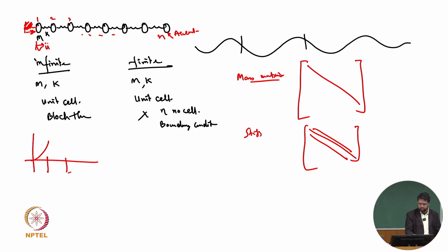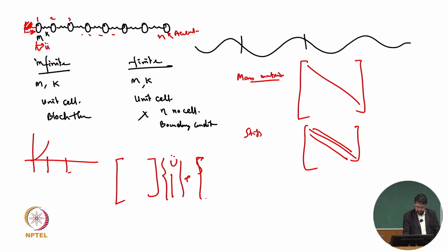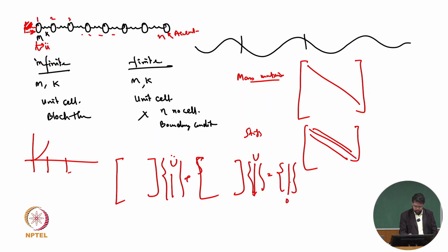Okay, so if that is our objective, then what do we have to do? We have to apply the force at the first node. We can write the mass matrix into u double dot, that full thing, plus the stiffness matrix into u, that complete thing, equal to all 0. Because with the shaker, once we give the excitation, that excitation is like a displacement we put at a particular point, and that column will eventually come to the right-hand side, and the first row will be cancelled.